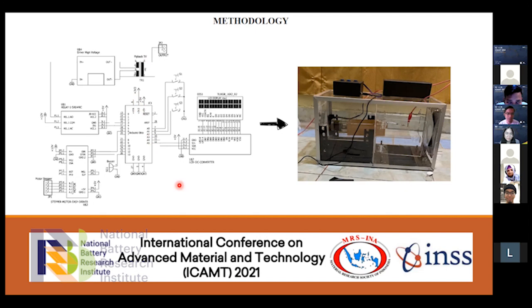An LCD with a size of 16 times 2 is used as the display, and the microcontroller can provide data directly to the LCD, which is equipped with a driver to convert the ASCII output data of the microcontroller into a character display.